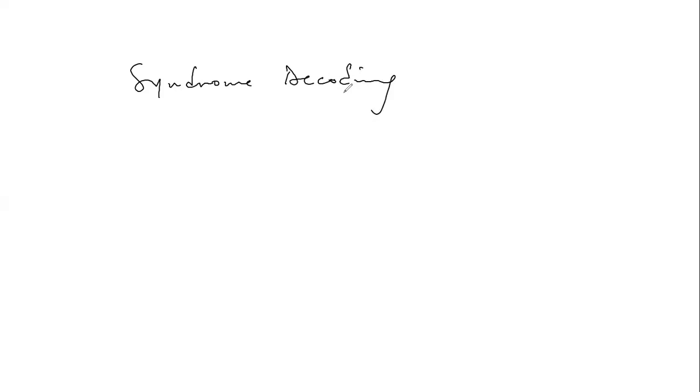So if we use the generator matrix to encode or generate our code words, then through syndrome decoding, we are able to decode. I already explained how this works. We already know that the code word is the same as MG, and that G H transpose is the same as 0. So if what we receive is the code word plus the error introduced by the channel, then the syndrome is the received word times the transpose of the parity check matrix.